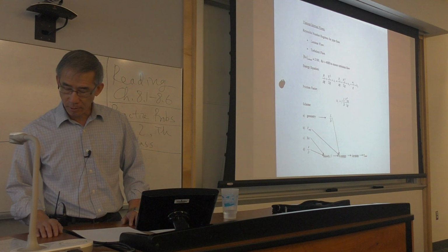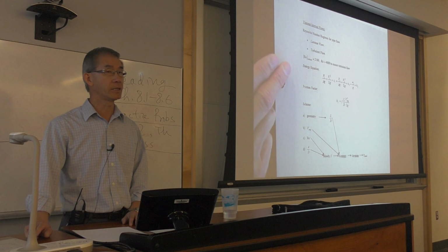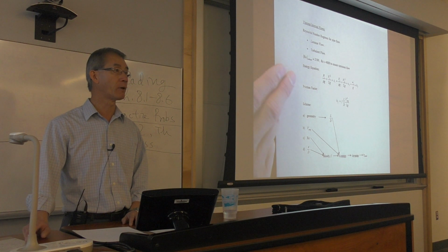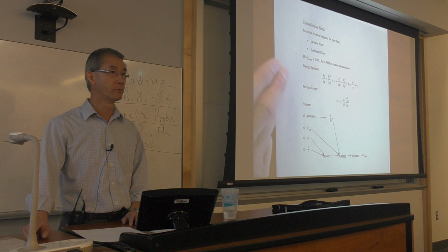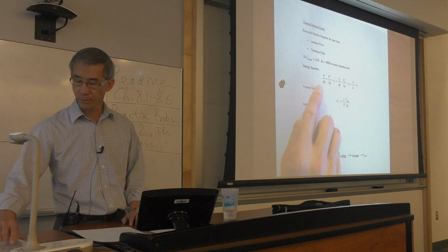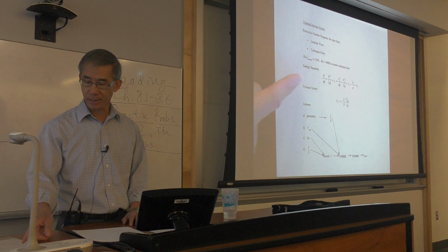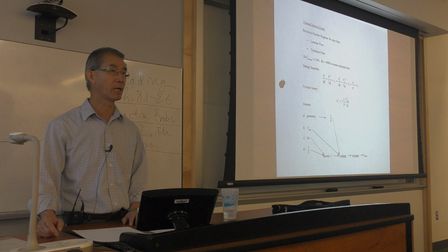And most importantly, we went through a very detailed derivation of the energy equation from your first law in the control volume in thermodynamics. And you should be comfortable with the origin of all the terms that are now cast in a way that is used for analyzing pipe flow.